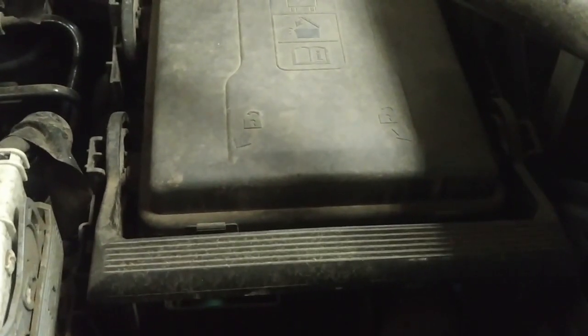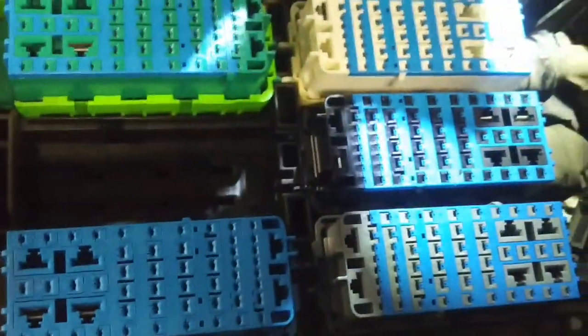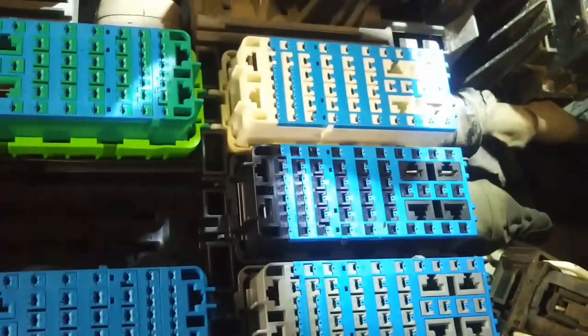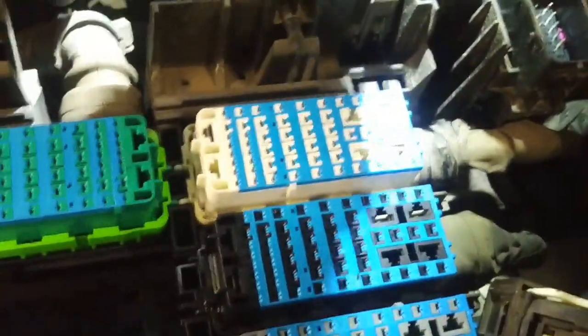So we're going to have a look at the fuse panel on the other side over here. See if there's any corroded fuses or corroded relays in here. So I got the fuse panel out of this thing, and it looks absolutely pristine. No signs of any corrosion or connection issues under there. And this main feed cable coming in appears to be clean and tight. No oxidized terminals. The cover looks like it was well sealed.